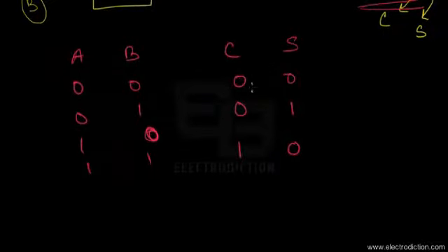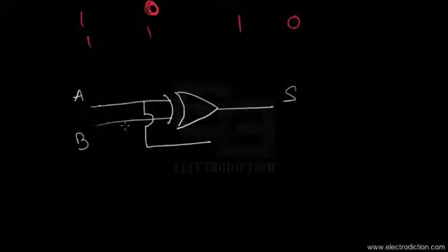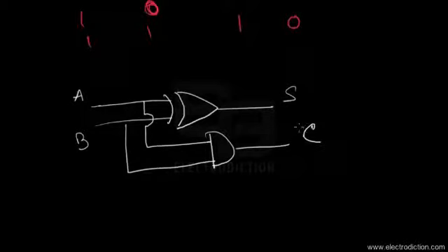Based on the pattern of output generated in the truth table of a half adder, we can construct its circuit by using just two very simple logic gates. We would require an XOR gate, that would produce the sum of the half adder circuit. The inputs to the XOR gate represent the input binary bits A and B, and along with it we would require another gate, the AND gate, for producing the carry of the half adder.